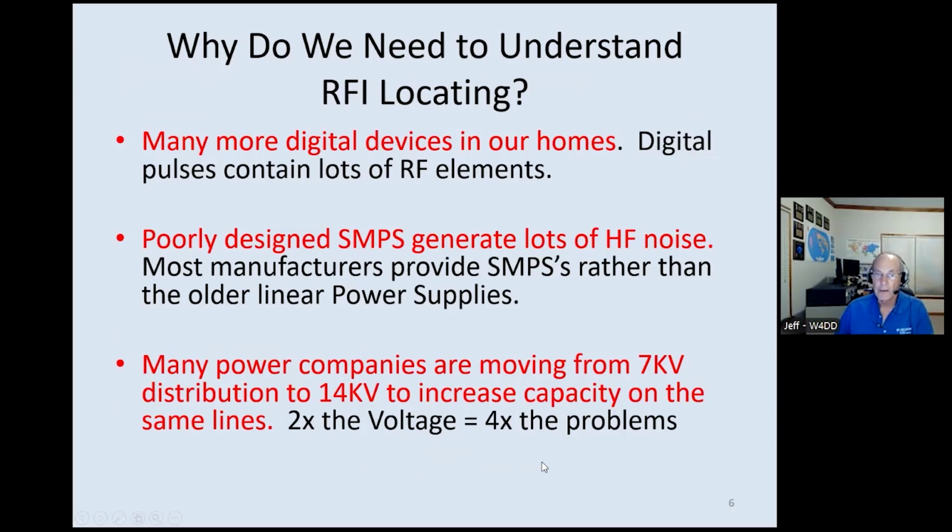So why do we need to understand this? Well, a lot more digital devices in our homes. Digital devices have lots of square waves. Square waves have lots of high frequency components that range into the RF spectrum. Poorly designed SMPSs generate lots of HF noise, and they try to push that cost lower and lower, and sometimes the parts that should be on the board are not on the board. So if you get a good one, that's great, but maybe 10%, certainly 5% of the SMPSs I see are problems.